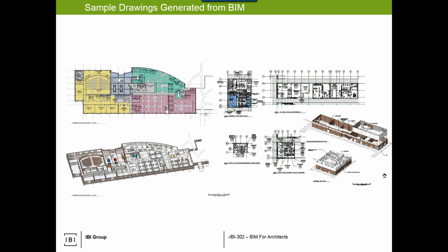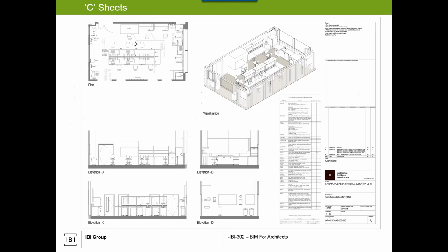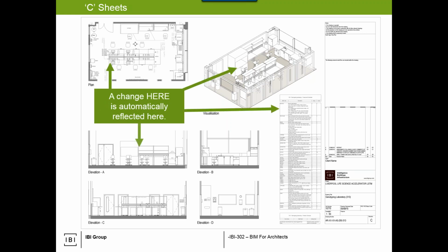You can generate different types of drawings, plan views for programmatic, planimetric 3D views, sections, elevations, isometrics, the premise for, or the basis for details, all from the same components. The C sheets, this is a UK example, C sheets showing the arrangement of components within a structure. I like this example. They made this over there because it shows you update it in one spot and it updates everywhere. That's the other beauty of BIM.